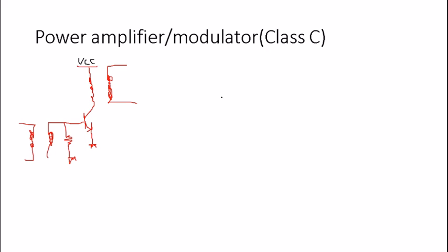But before getting into that, we need to know what the voltage that comes out of an AM modulator is in general. So the voltage that comes out of an AM modulator is v(t), which equals E_c, which is the amplitude of the carrier wave, times (1 + m cos(ω_m t)).